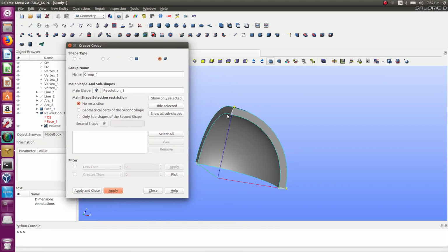Now I have to add one group for each of the surfaces. I will have nothing applied to the external surface, so I won't need that one, but I need these two to create a symmetry and that one to block it. So let's do that. Face, let's select this one and give it a name that I will remember. Let's call it sim x and z. Let's do the same with this one. Let's call it sim yz.